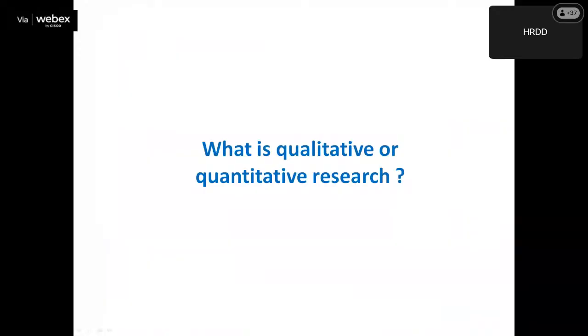They do it by methods like EDXRF. You can do quantitative analysis, but first you can do an energy dispersive scan. Throughout the energy range you scan, there will be peaks wherever an element is present. Or SEM, scanning electron microscopy, along with which there is EDX, energy dispersive X-ray. He is handling that equipment also. You get the X-rays, which are characteristic of elements, so you can identify the element.